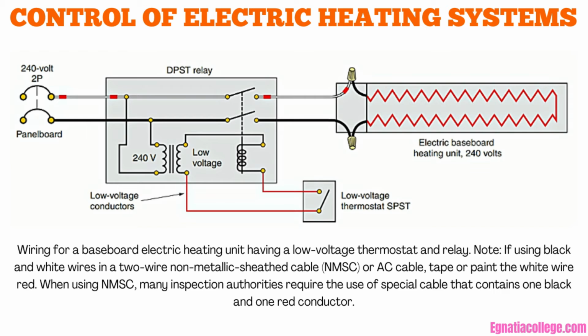In general, contacts and relays serve the function in the electrical industry of using a low voltage or low current to control a much higher one. This is done for safety and to lower expense, as the smaller control wires of a relay or contactor are much cheaper to run than the large conductors that bring power to heating or cooling devices.